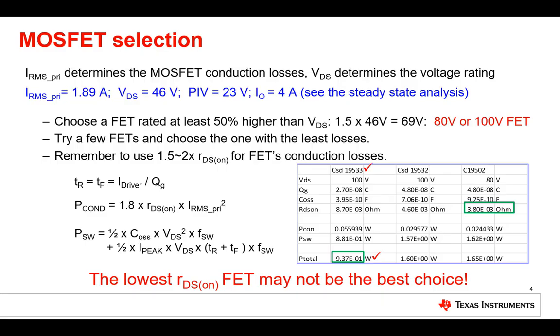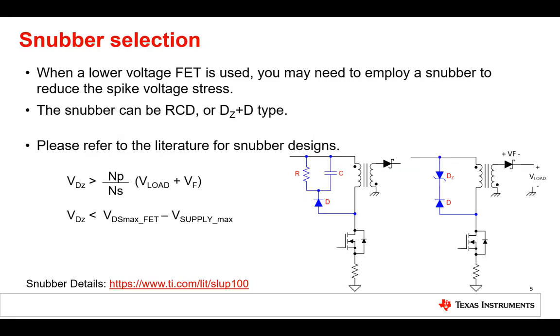Especially during EMI testing of the flyback, it might be necessary to reduce the rise time of the switch, and these tests are often done late in the design, so PCB changes might be painful. For every flyback converter, I recommend placing the components for a snubber across the primary winding. It might not be necessary, but if needed, it is good to have the footprints available on the PCB.